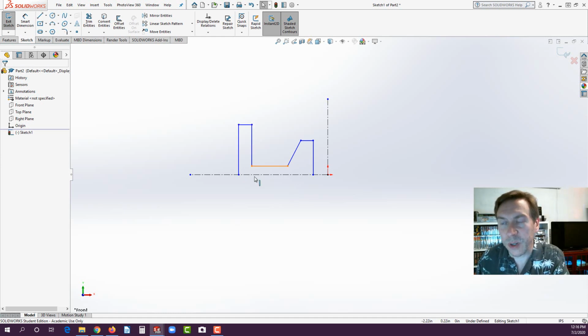So what we're going to do now is we're going to learn how to mirror sketches across. Again, this is a review to those of you who did Lab 1B. So the way it works is you need a center line when you're mirroring 2D geometry across. And we have that. That's why we drew that. It's the horizontal center line. The vertical center line, by the way, is actually going to be used to revolve or spin it around. So we're not interested in that one just yet. But let's get this mirrored across.